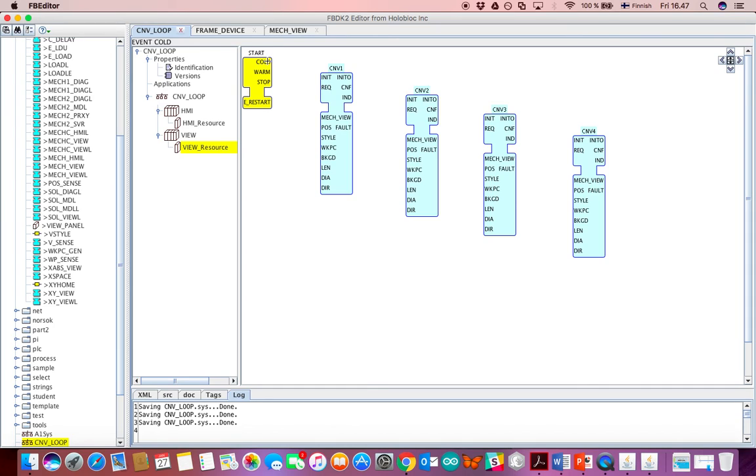So I interconnect now, cold, when we power up our device and its corresponding resources. I am pressing down the Alt key on my keyboard and drag and dropping an event connection between cold and the init input. Then I take the init output of scene v1, press the Alt key down and drag and drop my mouse to interconnect it with the init input of the next block.